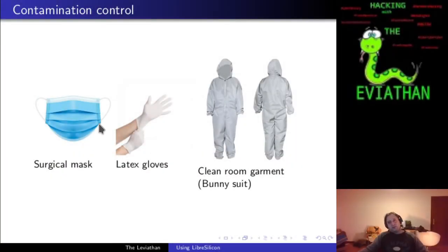So if you really want to go high tech, submicron, 500 nanometers or less, you should really wear proper cleanroom garment in a cleanroom environment, wear latex gloves and surgical mask. And again, that's not a political statement, but if you don't do that, your circuits will just not work.